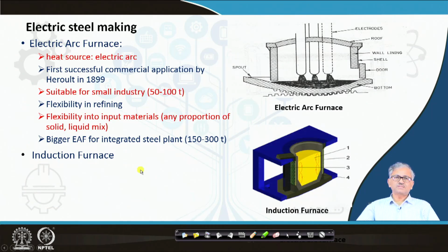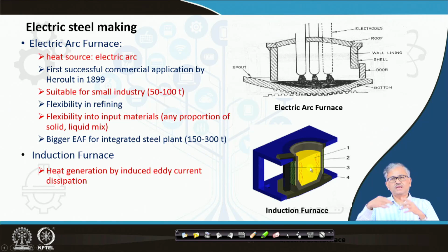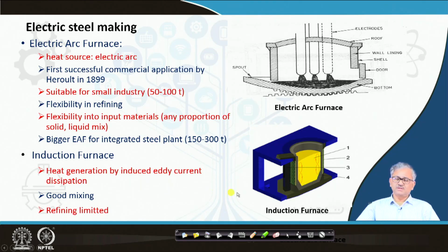Induction furnace, as the name suggests, basically heat is generated by eddy current dissipation in the metal. Eddy current is generated in the scrap or whatever metal you are charging, and that will melt it, and it has very good mixing. Refining is limited; I will talk about that. So this is your induction furnace.